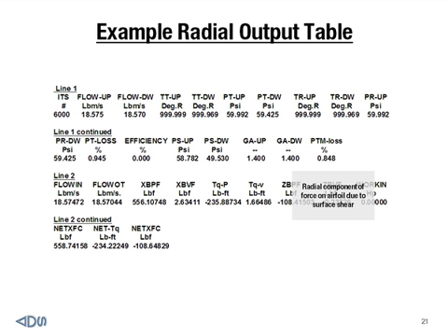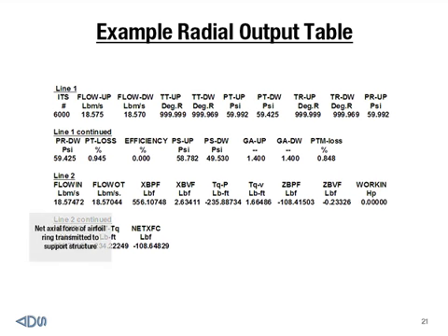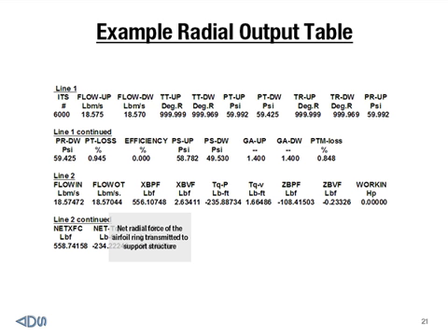And again, radial component of forces on the airfoil. And all these definitions are provided in the user manual. This next term is the power extracted from the airfoil row. This is the net force, pressure and shear forces transmitted to the structure, the net torque transmitted to the structure, and the net radial force.